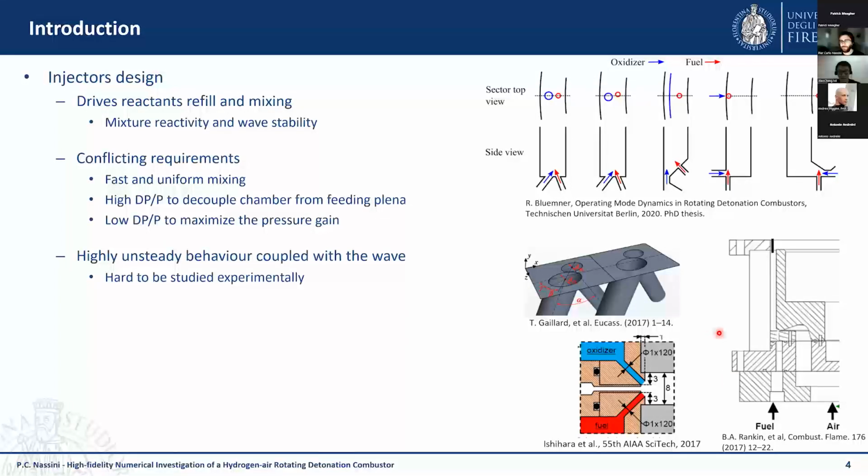But also, in my understanding, it is because we don't know how to characterize the pressure gain of such unsteady flow at the outlet. So this is, of course, a part which should be clarified when we think about integration to the turbine, because the turbine wants to have mostly, I don't want to say steady, but as stable as possible a flow, which is pressurized. So a very high speed flow is not, of course, optimized for the turbine.